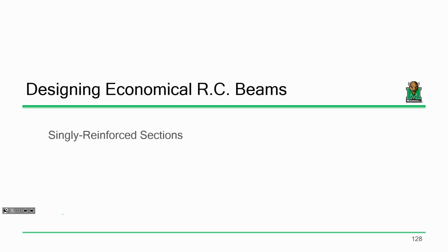We had this discussion last time in steel design. What we did just now is assess, given a beam, how strong it is. Now we're going to say, based on a span length and some loads, how do we size that beam? We're going to do this 2 different ways. One, how do we design the beam if we don't even know what the cross-section looks like?